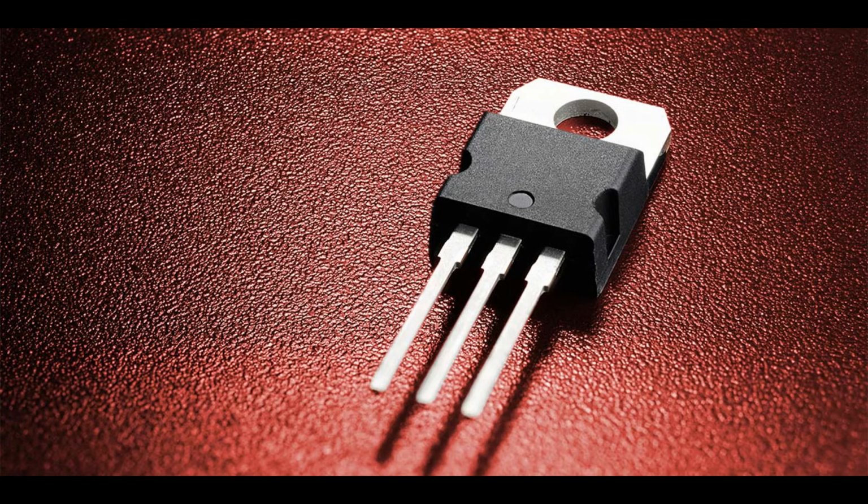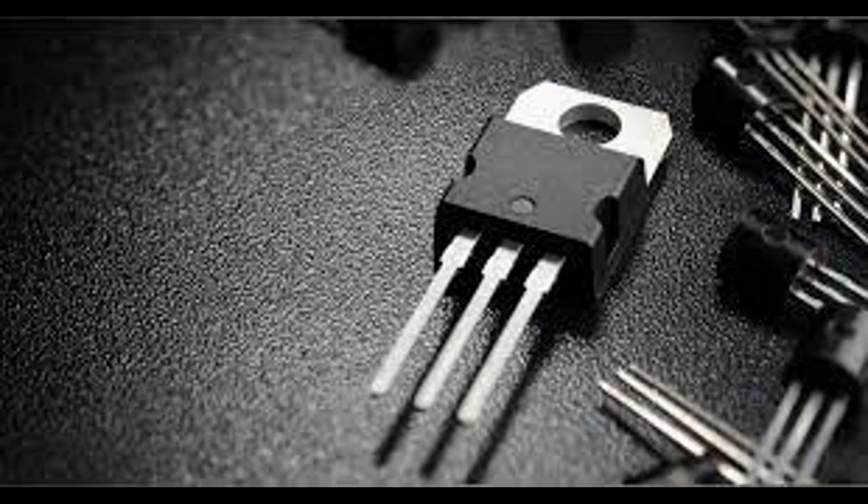1. Terminals. Gate, G: the terminal that controls the MOSFET. A voltage applied to the gate creates an electric field that modulates the conductivity between the drain and source. Drain, D: the terminal through which the output current flows when the MOSFET is in the on state. Source, S: the terminal that supplies the current to the load. In a typical application, the source is connected to the ground.